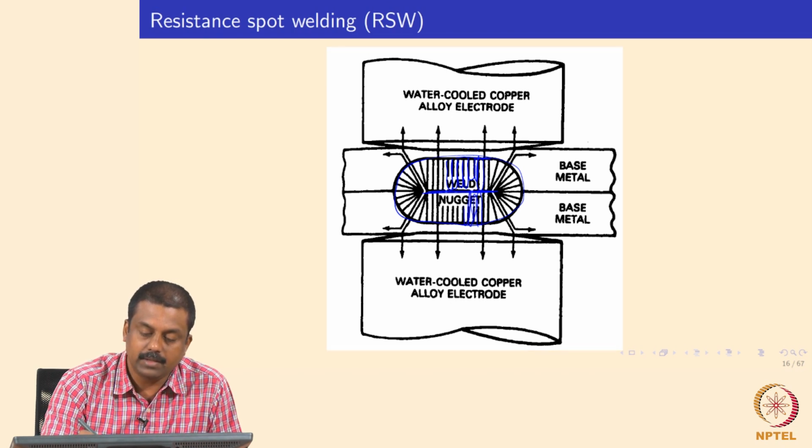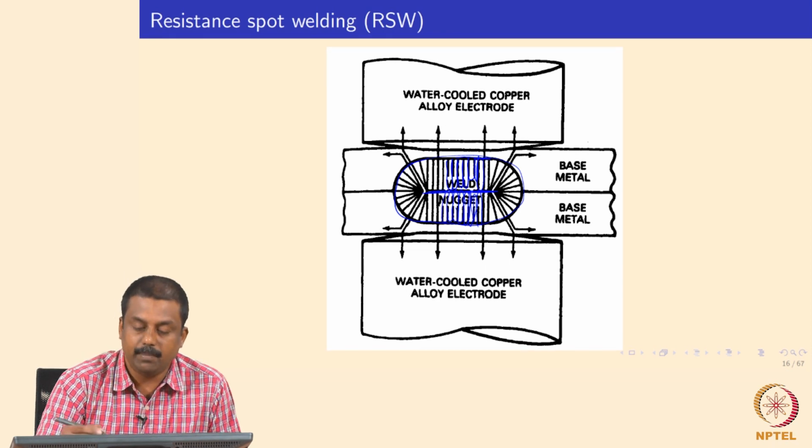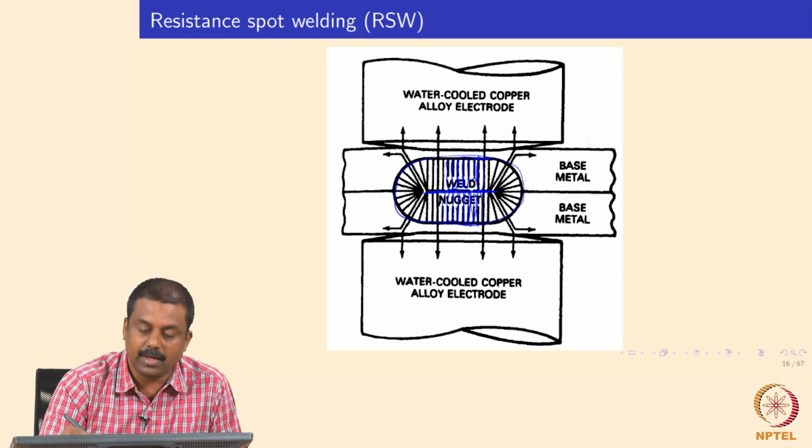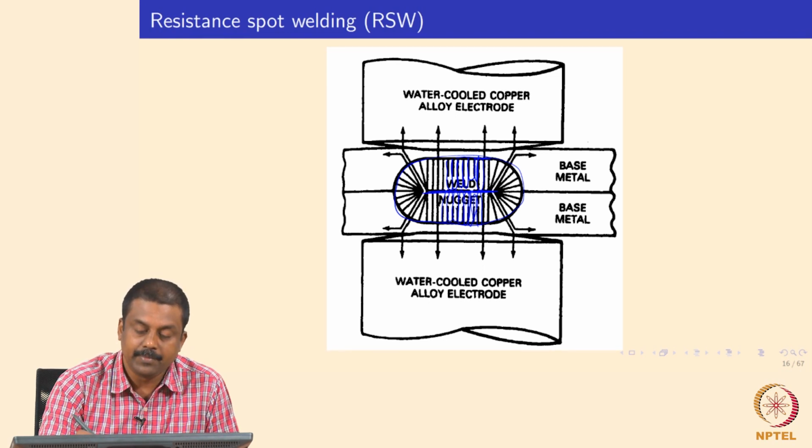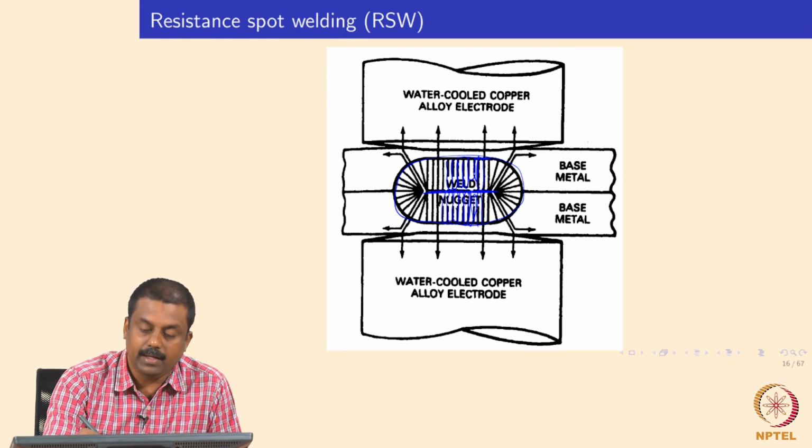This structure is not metallurgically preferred because of the very strong segregation that develops during solidification of the columnar grains. During this process, alloying elements that prefer to segregate to the liquid end up enriching the solidification grain boundaries as well as the weld center line.